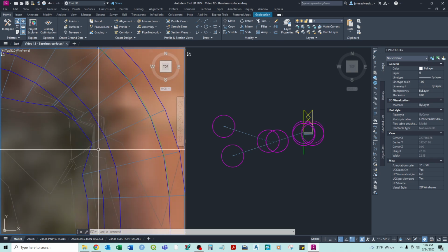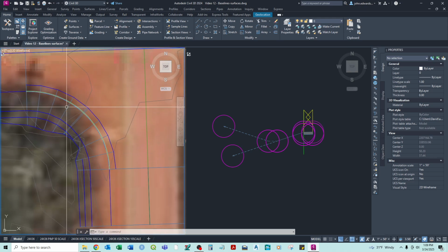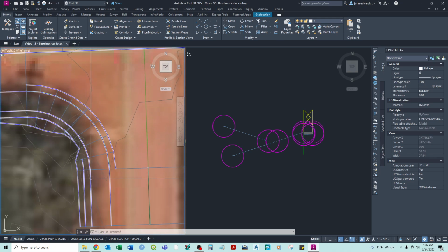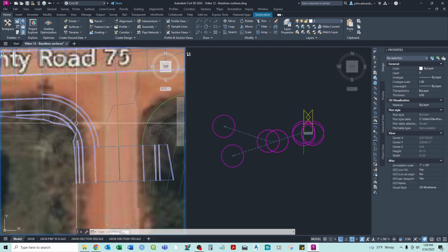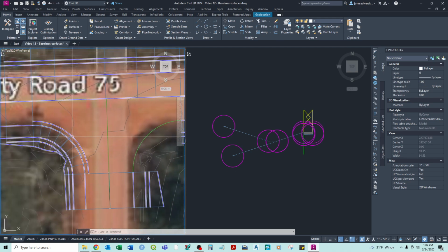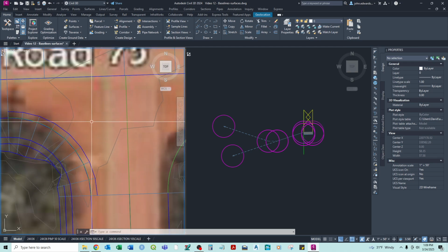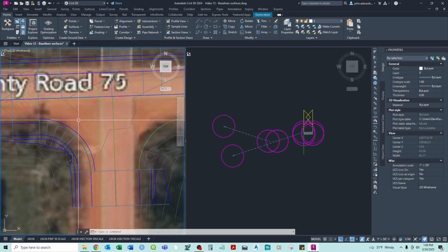There's actually a head wall coming in here, but just for a general representation, we've matched our ditch coming around the corner, and we've matched our side slope. But right now, our lane only goes 2 feet around the corner. We want that lane to match our center line crown for both of these features.